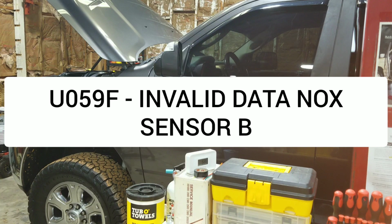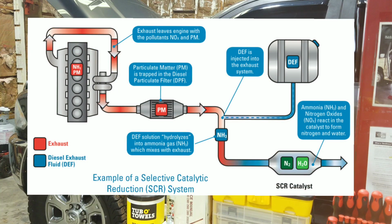That's coming back as the NOx sensor, or the nitrogen oxide sensor, in the rear of the selective catalytic reduction pipe, basically like a catalytic converter, in the very back of it where the exhaust gases exit. The sensor gives the computer a comparison from the input to the output, how much the pollution was reduced.